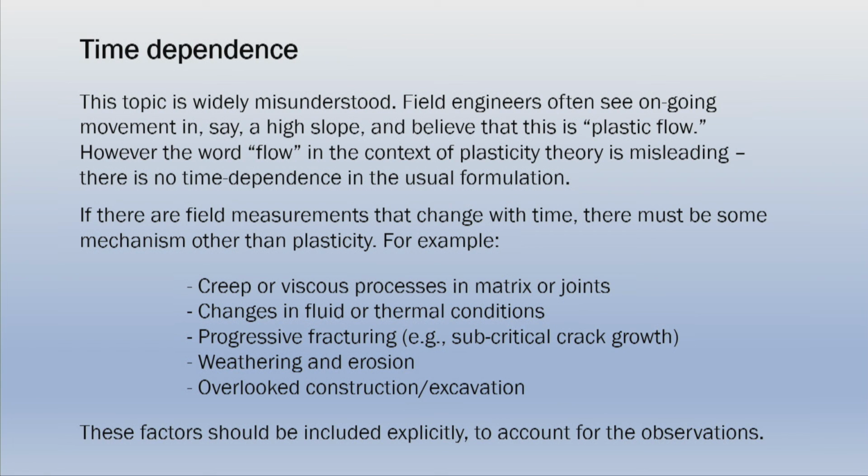And they then said, well, you can model it with plastic flow. Well, no, you can't, because plastic flow in regular plasticity theory has no time dependence in the usual formulation. It flows and then it stops. And they didn't understand this, and these were pretty experienced engineers.